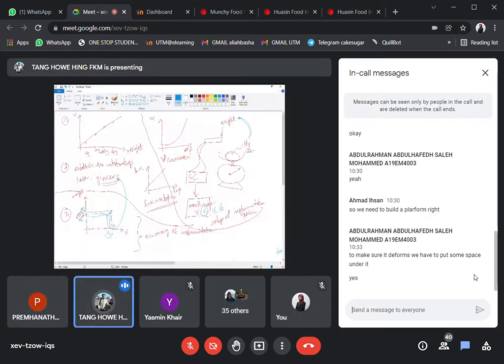Okay, so step 1, it means that this weight has to be a standard weight. You still remember just now, I mentioned the standard weight could be 1 kilogram of rice. Okay, so you just hang 1 kilogram of rice at the load cell, then in that case you are going to get this reading. And then 2 kilograms of rice, then another reading. 3 kilograms of rice, another reading. Okay.